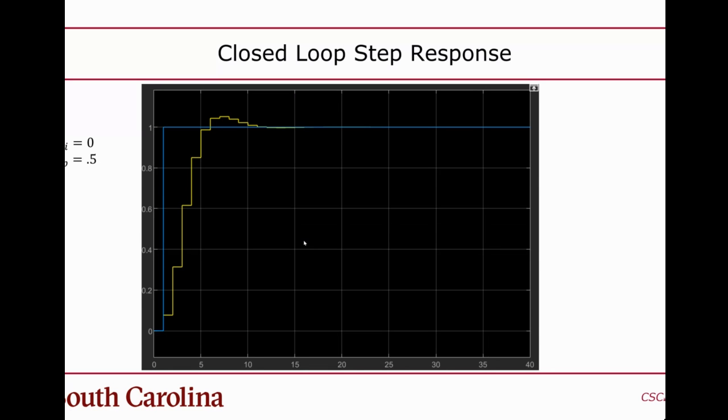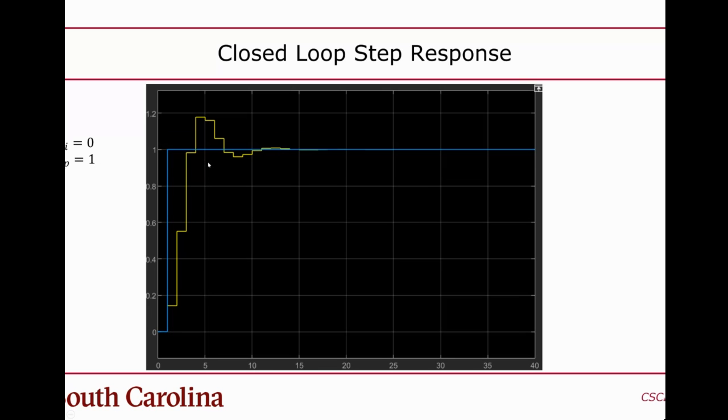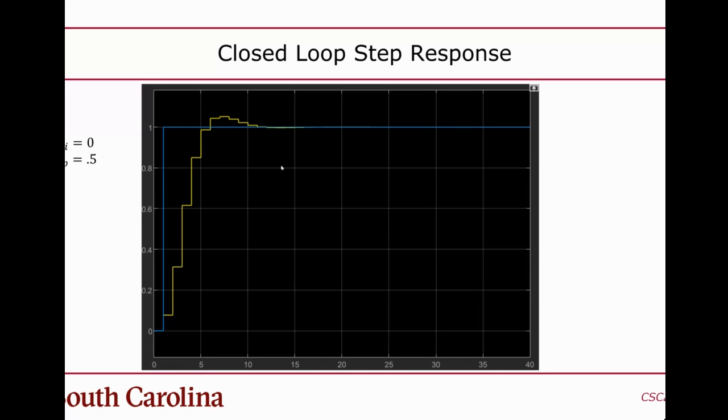And then I tried setting Kp to 0.5, so I brought the proportional down a little bit, and you can see that made the rise time worse, but it limited the overshoot. The overshoot is less, but the rise time is worse. So I traded off rise time for overshoot by doing that adjustment. This is all just tweaking these parameters manually. And so that's all we've got.